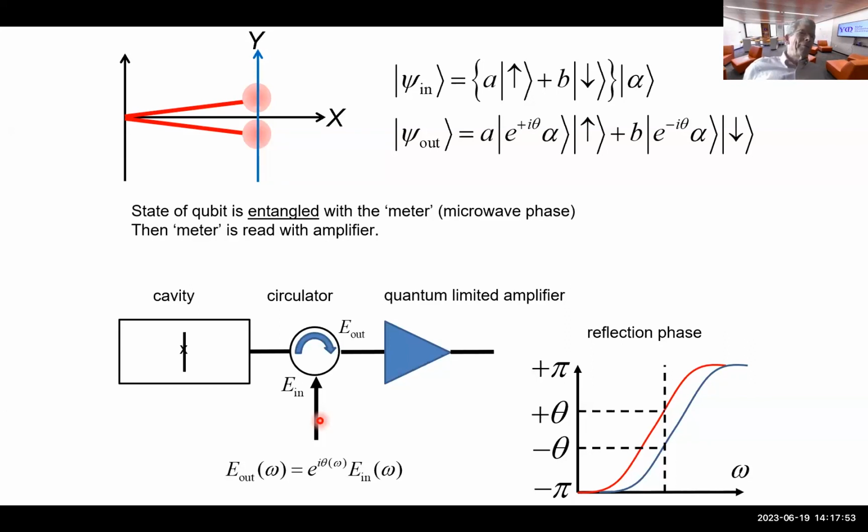On the other hand, if you couple your transmon to a low Q cavity, it may spontaneously radiate out through that. That's the Purcell effect. So you have to do some tricks to put in what are called Purcell filters or some mechanism that lets you do a fast readout, but don't get a corresponding fast decay of the qubit.